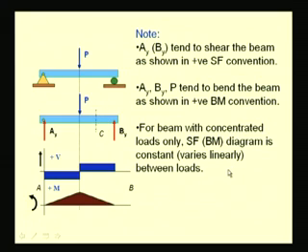So, these behaviors can be used to plot the shear force and bending moment diagrams conveniently by determining the values of shear force and bending moments at locations where we have concentrated loads, and in between we can plot using these behaviors, that is, the shear force remains constant and bending moment varies linearly for these concentrated loads.